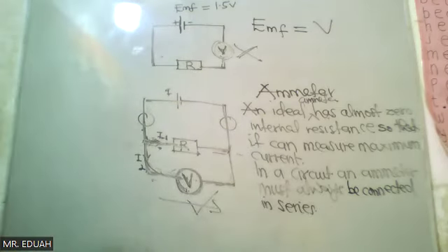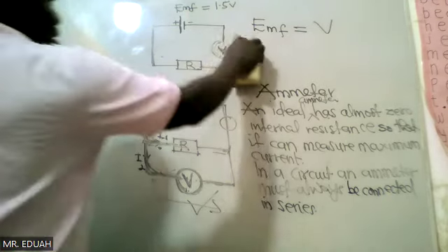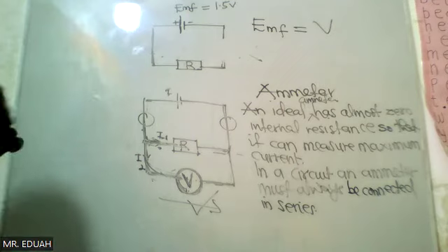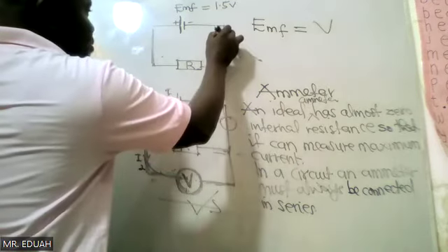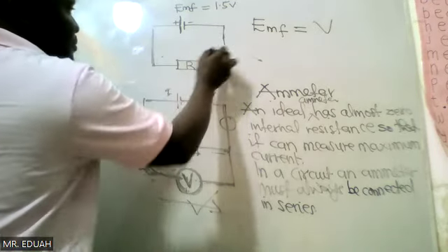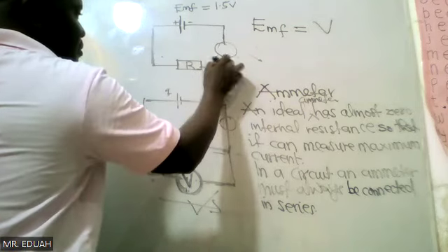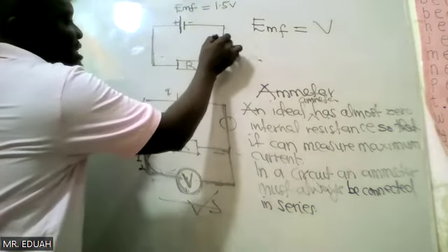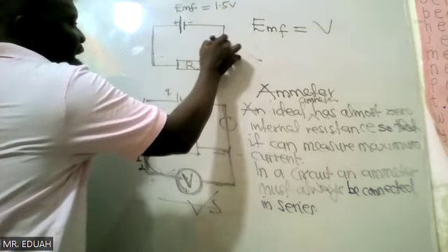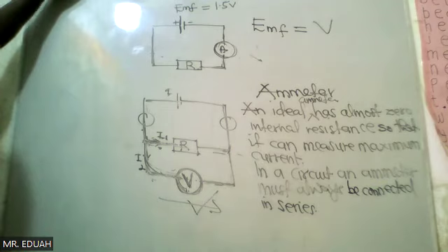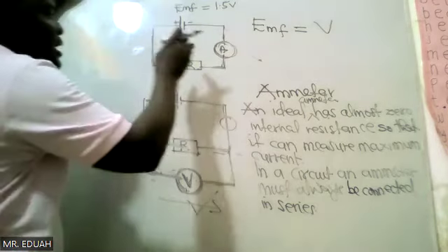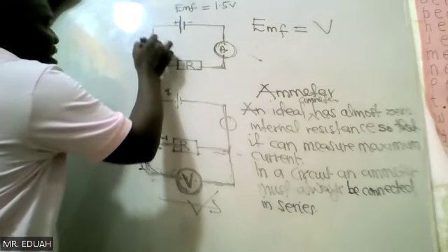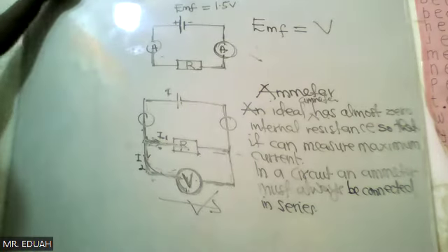So let's come to this circuit. If I have a circuit with a resistor, to measure the current flow, I must connect the ammeter in series. Here, break the circuit, either this part or this part, and push it in, whichever way would work.